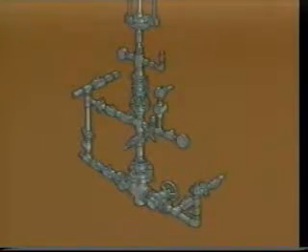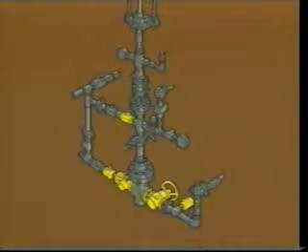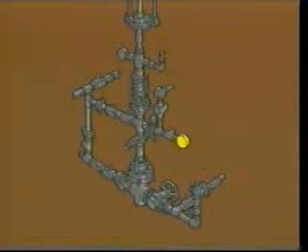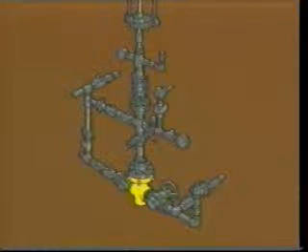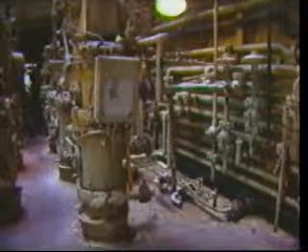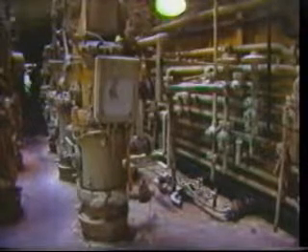The basic components of a typical pumping well are blowout preventers, possibly 3, that fit the polished rod, a pumping tee, a stuffing box, and gate or ball valves, followed by check valves. A safety shutdown switch and a pressure gauge are located on the pumping tee assembly. The casing annulus is tied into the flow line so that natural gas can be produced at minimum pressure without interfering with the downhole pump. Other types of artificial lift, for example electrical submersible or hydraulic pumping units, require special design consideration with respect to